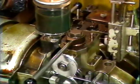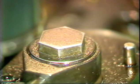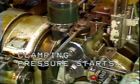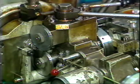This is the pressure adjusting screw for the stock clamp lever. Pressure on the stock must be adjusted after changing stock feed rolls and stock size. When properly adjusted, the stock clamping lever will begin to clamp the stock at the midpoint of this portion of the machine frame. You should feel the pressure increase as you pass this point.